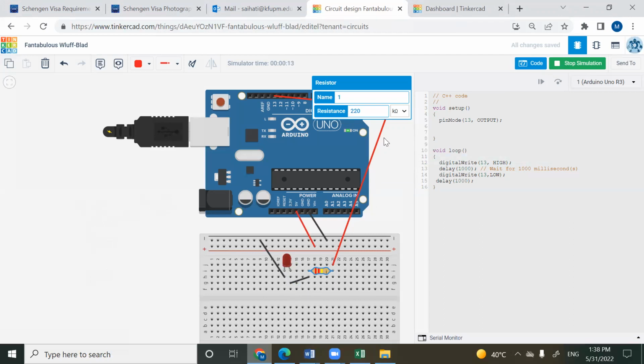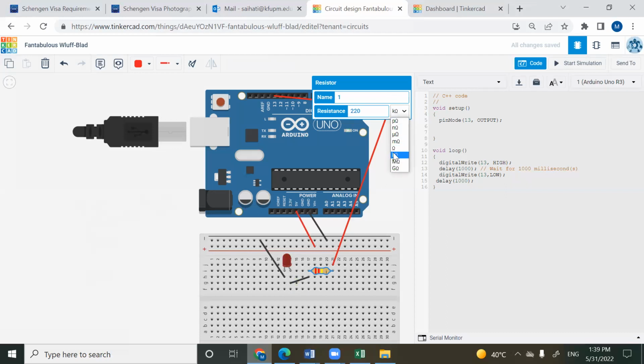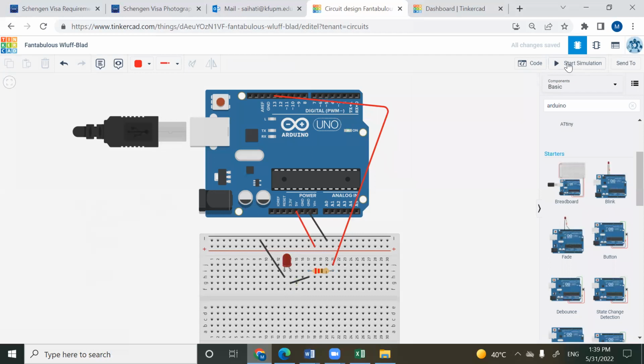So high resistance is good for the power, but it is too big for you to be able to see the LED turning on and off. Okay. That's why I always make sure that you use this one as on, because the current is very little when you increase the resistance. Yes, you need a moderate amount of current. So I think 220 to 330 is fine.